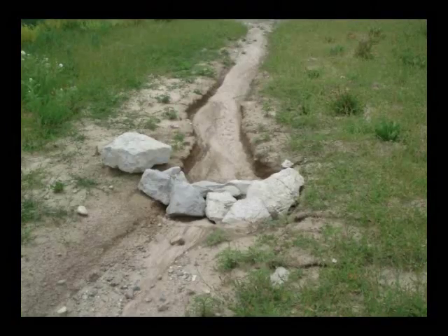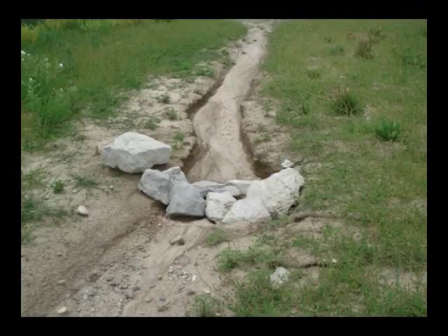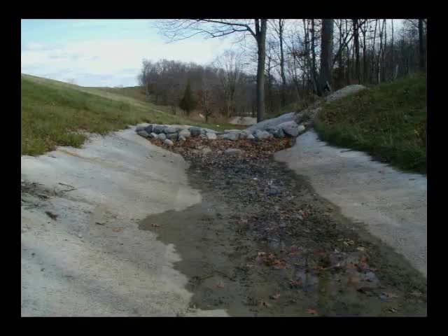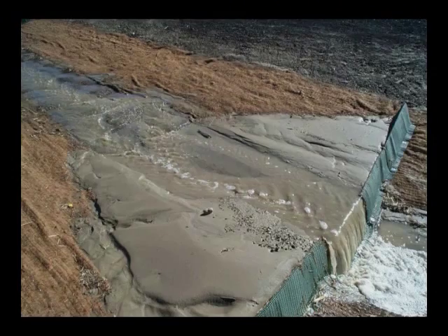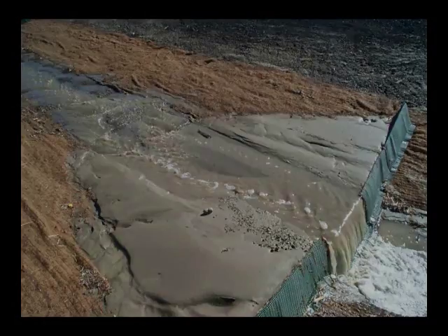To ensure that the check dam is properly constructed and functioning, the inspector will want to examine the channel bottom and sides of the check dams for erosion. Accumulated sediment on the upslope side of the check dam, or in the sump, should not exceed 40 to 50% of the original volume. If temporary check dams are used, be sure they are properly secured to the ditch bottom, are not damaged, and are not obstructed by debris. When the channel is well stabilized, schedule the removal of temporary check dams.